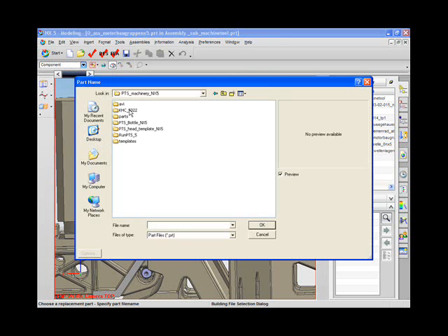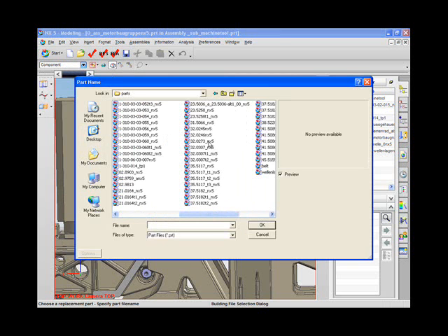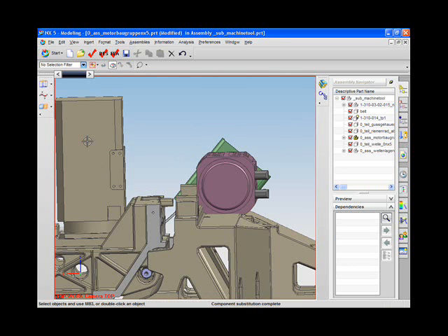So if we pick this motor here, you can see that the spacing allowed for the original motor is no longer valid for this motor. And so what do you do in your company at this point? So you either have to go back to the drawing board and find a motor that is of the same size but also a more powerful motor, or you can go with this motor and have the engineers who designed the bracket modify it so that it can be stretched to include spacing for this motor.